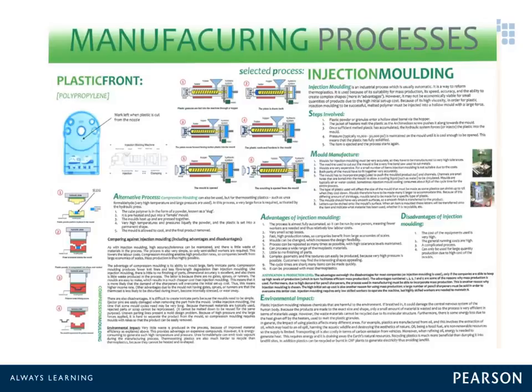The slide shows a well-presented sheet describing injection molding and an alternative process, but all of the information is generic and not focused on the manufacturing or design needs of the product. Perhaps a more appropriate response would have been to point out such things as the need for the product to have a complex, thin-walled shell that required screw sockets integrally molded to receive fixings, so that it could be joined to the main body, and the only way of achieving these features would be through injection molding.